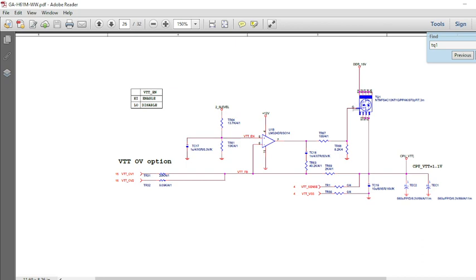You have to check whether the gate supply is available or not, and whether it is coming for a few seconds and going. If it is coming for a few seconds and going, it's okay. Next, you have to check the voltage. This is the supply you have to check on TQ01. This will be near, below our CPU socket. This MOSFET is available, so we have to check that.